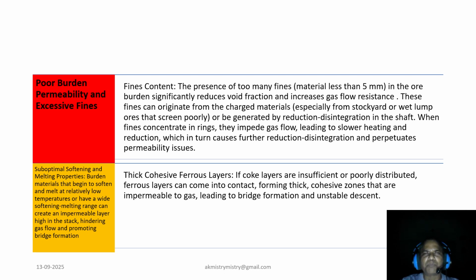Similarly, poor burden permeability, often due to excessive fines content, material less than 5 mm, as we have discussed in our earlier presentation, also reduces void fraction and increases gas flow resistance. These fines come from charged material or reduction disintegration, where one is the fines carried from the raw material source, and another is the low temperature breakdown.